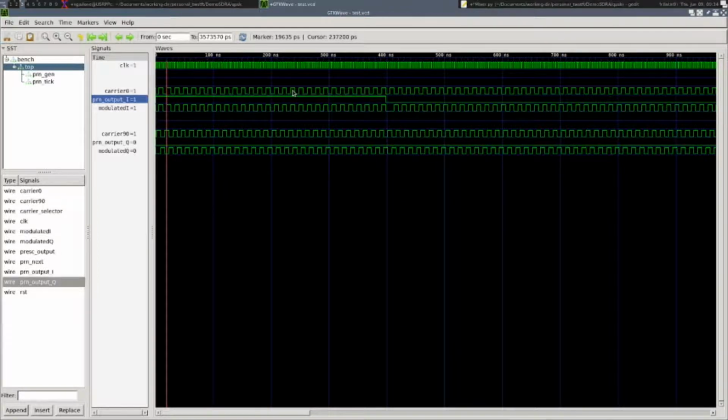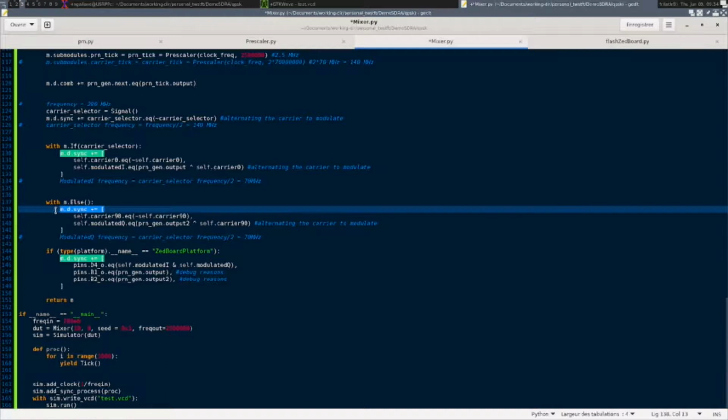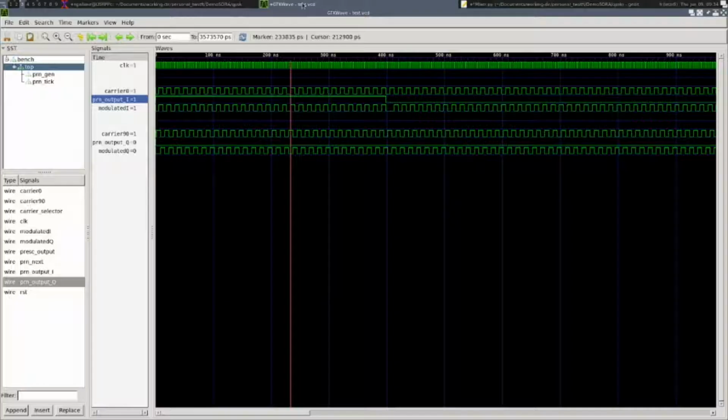So you may ask, what's happening? Why do we have here a high state and here a high state too, which makes a XOR? So XOR high equals normally low state. But here, remember that the rule we created here is a synchronous rule. So in fact, the operation only applies for the next tick, which is at the end of the higher state here.